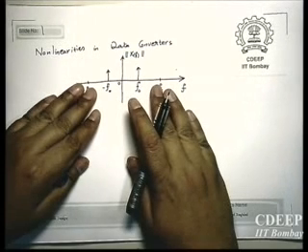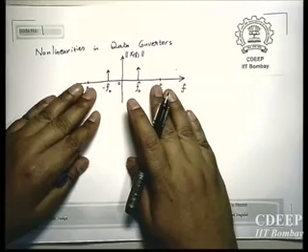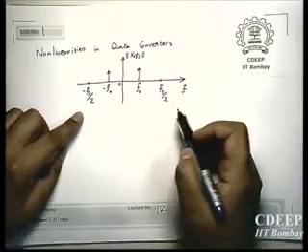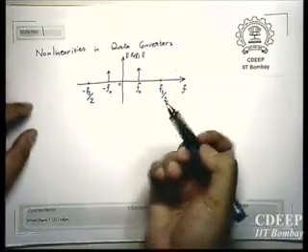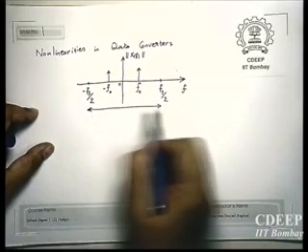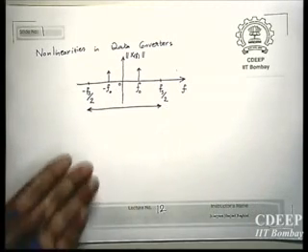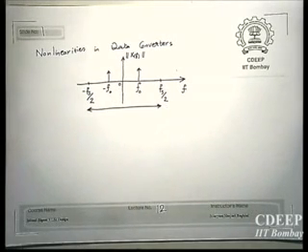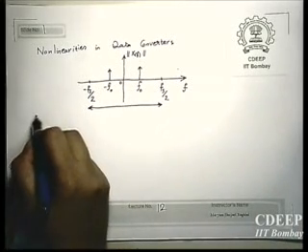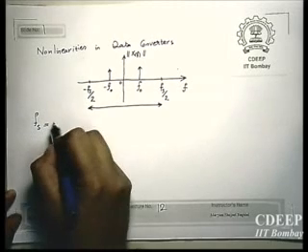Now before sampling, you have this signal. If you have nonlinearities, you will have harmonics, so your signal is not limited in bandwidth. Now you will sample it, and after sampling this is your effective bandwidth. So how can you get harmonics over here? Notice, in this example your sampling rate is 200 megasamples per second.